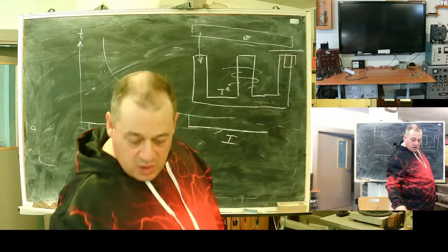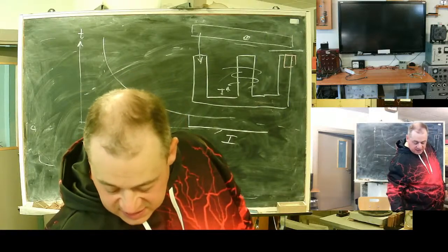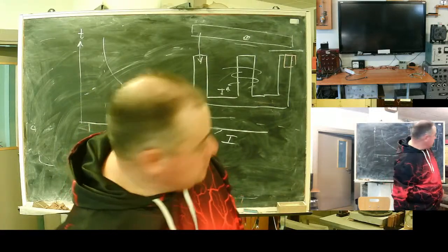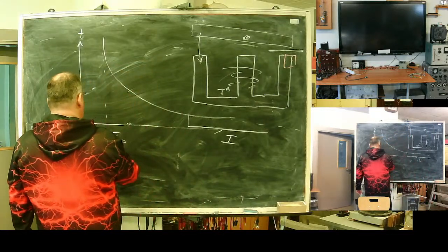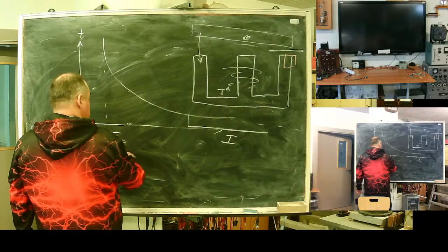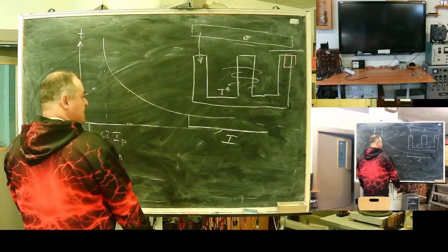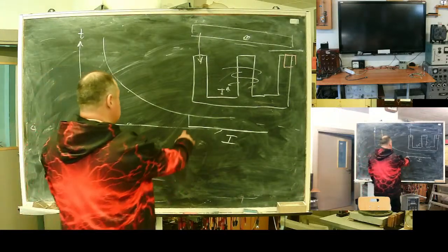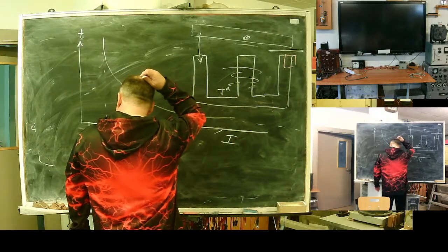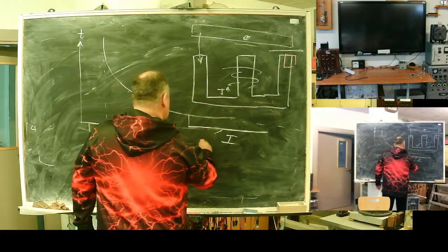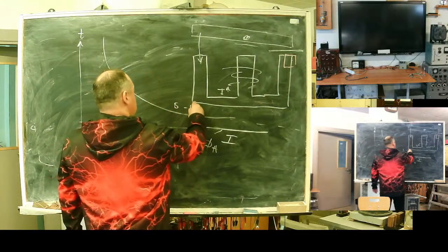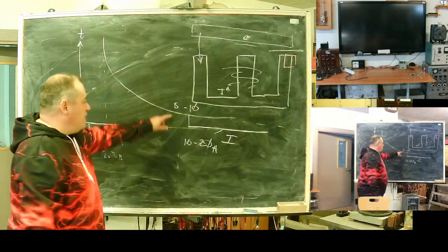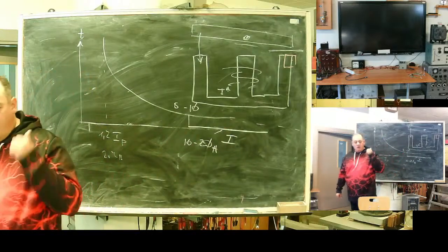For this one, if it's set, so for mine, this will be something like 2.4 amps, because the plug is set to 2 amps. And here approximately 16-20 amps will be the trigger, 8-10 times, when it's triggered instantly.